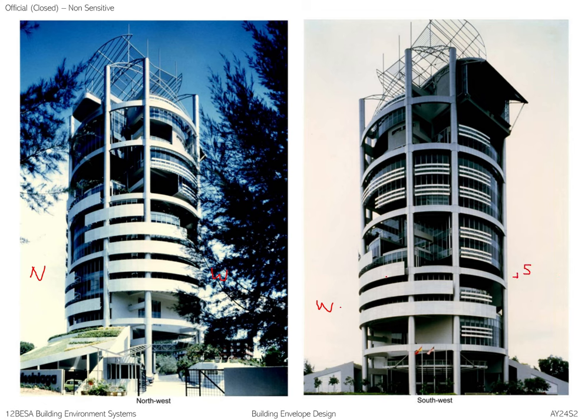You can see in terms of the sun shading devices, there are a few standard components. You have solid panels, you have linear panels, and then you have the curtain wall right inside. You can see how he responds to the west versus the south. The amount of transparency in this face versus this face, the strategy is very different. The south is relatively transparent, and the curtain wall is located close to the perimeter.